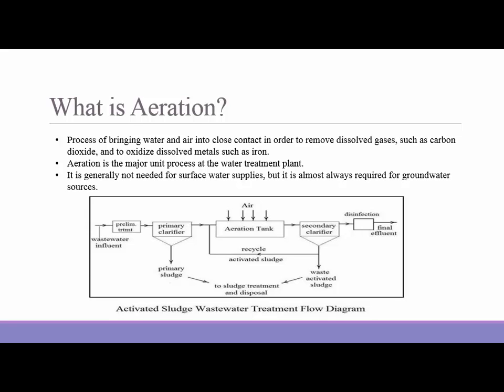Looking at the picture, we can see aeration is after the primary clarifier. So it is a major unit process at the water treatment plant, and it is generally not needed for surface water supplies, but it's almost always required for groundwater sources.